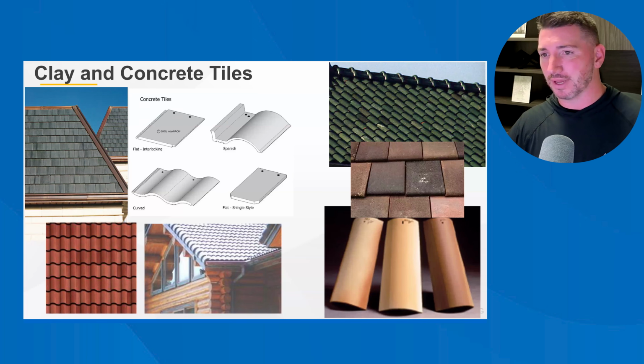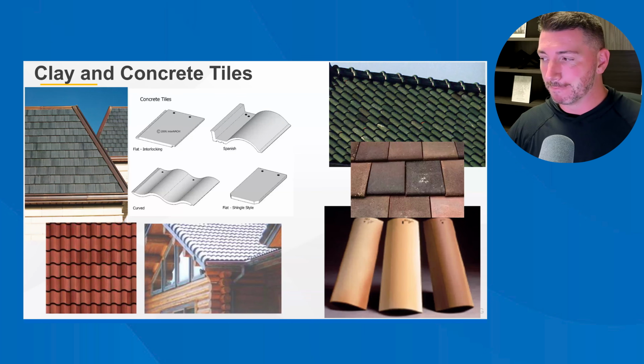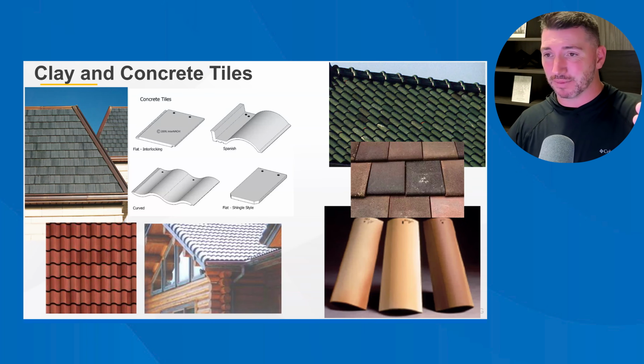Concrete tiles, depending on the thickness and the shape, if they're lay flats or interlocking ones, again, if they're interlocking, it's a little sketchy. You don't really want to walk on those interlocks because you put pressure where there's a gap and you could break off the tongue. But use your best judgment. If they're very thick and they feel sturdy, walk on the headlaps. Otherwise, stay the heck off of them. And the good news is they shouldn't be failing too much out in the field areas unless you can see that something's broken and laying out of place. But look in the change of direction areas.